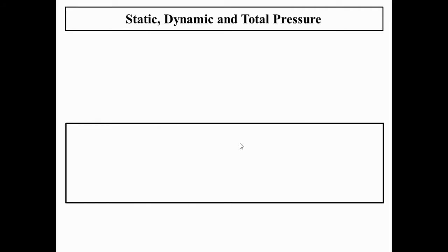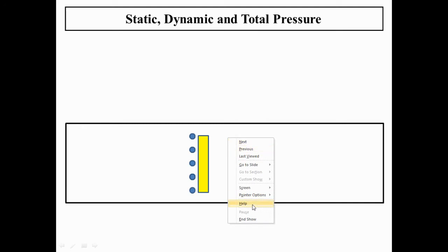We consider a flow happening over here, and then we have an obstacle over here. What would happen due to this obstacle? The flow would get separated like this because of the obstacle. You can even feel that when flowing water is going through a channel and you put your hand in it, you can find the separation happening around the surface. So the separated flow would happen.